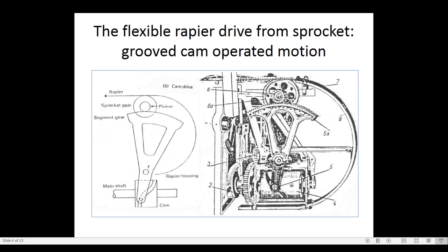So these drives are not connected, left hand drive and right hand drive. The figure shown is the right hand drive. The same duplicate figure, the drive, will be present on the right hand. So these drives are not connected to the sleigh. It is connected to the machine frame, and not movable, fixed. When the sleigh goes backside, at the back center, these Rapier tapes go to the middle of the machine and come to the side of the right hand side or left hand side. So for the sleigh the dual will be there.